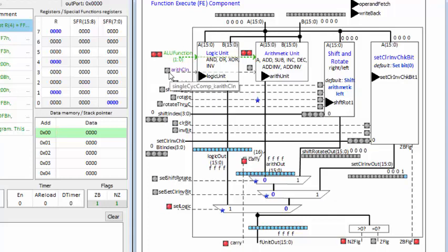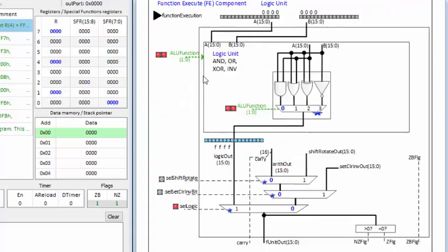So now I will look inside the logic unit, and the logic unit has A coming through. In fact, there's an issue in this drawing. The input to the inverter should actually be from A, from this path connected across to there. So I'll update that picture in the released images. It's selecting with ALU function both ones, path 3, FFFF is the result, and again out through select logic.